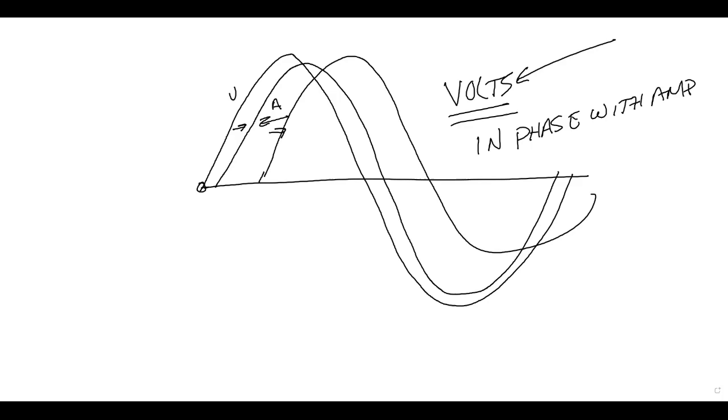Can I tell the customer to turn his motors on and off to help with my waveform? "Hey man, shut down four air conditioners at the college. You're disrupting our power system." That ain't gonna happen. But can I open and close the capacitor bank on my own system to help accommodate for a poor waveform? Yeah, so that's why. In that world, I can't make amps change. That's the customer doing it to me, but I can adjust my volts. And that's what a capacitor bank is there for.